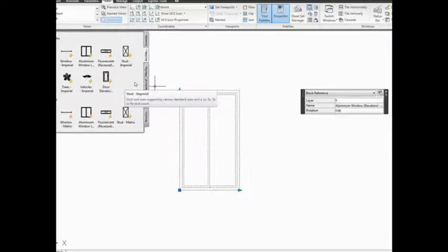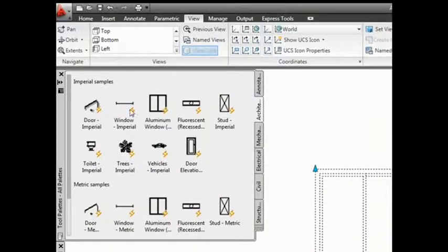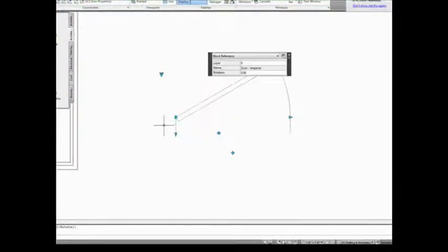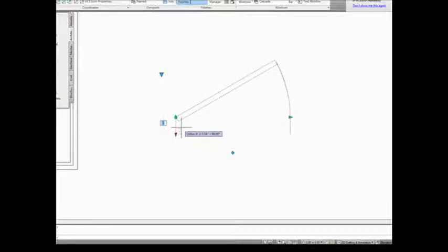Some additional blocks just to look around. You've got your door for a floor plan. And if you click on the door block, you can see your different grips. Now here we've got a few different parameter control points. We have these little arrows, or flip arrows, and they allow you to flip the block. So in this case, we can change which side that the door swing is on and things such as that. Here's another linear control. We click on that and we see this is to adjust for the wall thickness that we insert this block in. So we can insert it in different size walls if we would like.